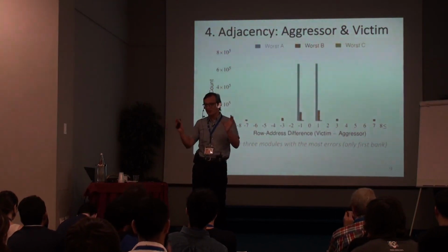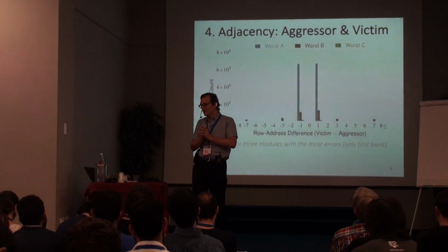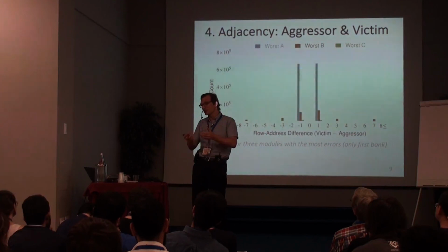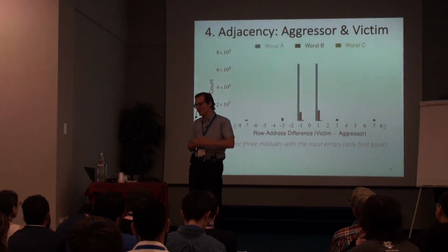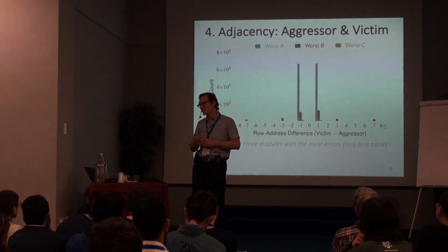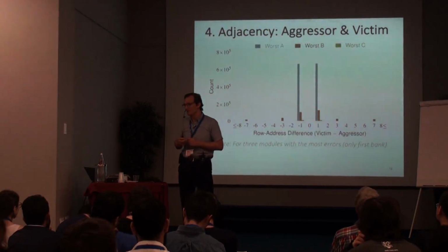And as you chop it into smaller ranges, the error rates certainly increase. And as a result, your endurance also reduces significantly. So certainly your memory becomes less reliable as you go into MLC, TLC, and QLC actually, if you want to store 4 bits per cell. There's no question about that. And that's very fundamental. But that's true for other memories also, like STT-RAM, phase change memory, yes.